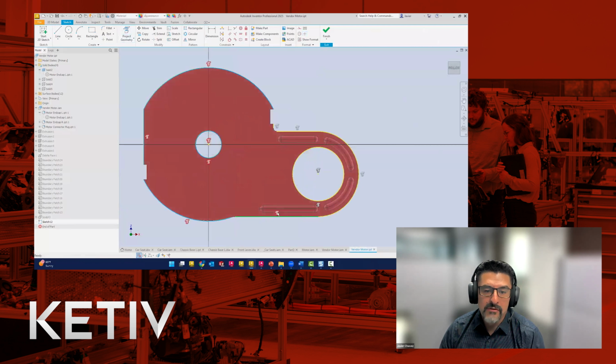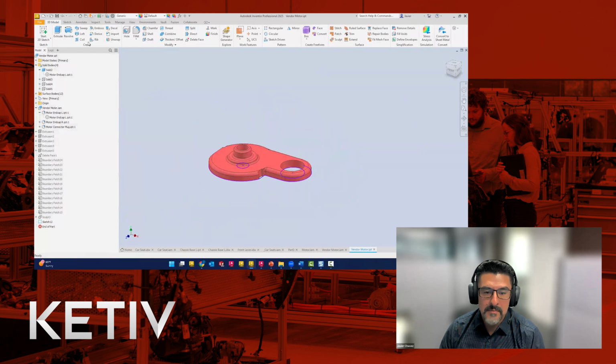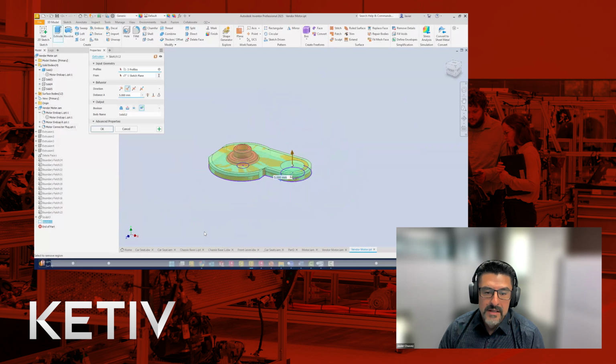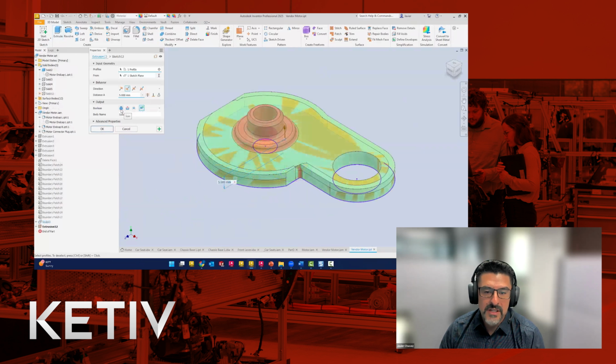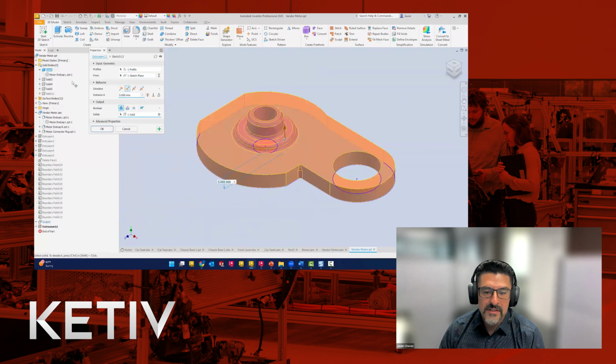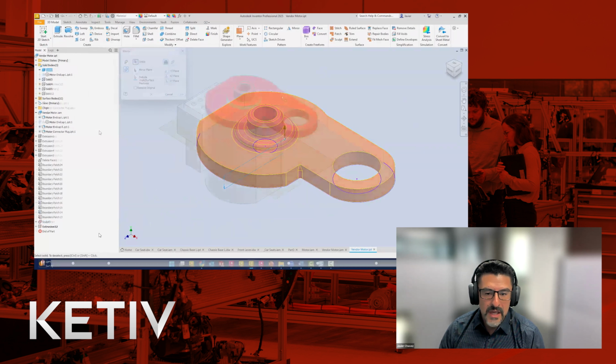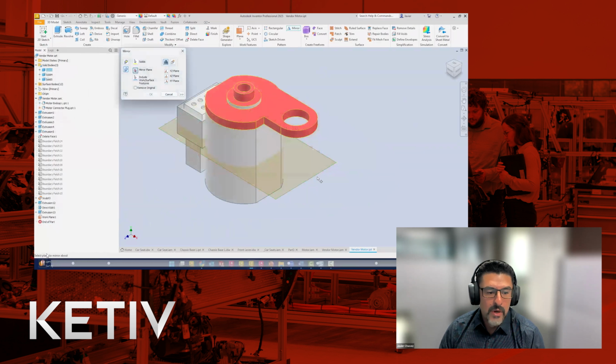And we are borrowing from the original, so we're borrowing edges, disassociating them eventually because that red part will go away, and we'll replace it with our own extruded version of the same thing. So again, you can see us going through that extrusion process, and in the end, what you're going to see is radiused edges going away, and us ending up with a simplified representation of this.